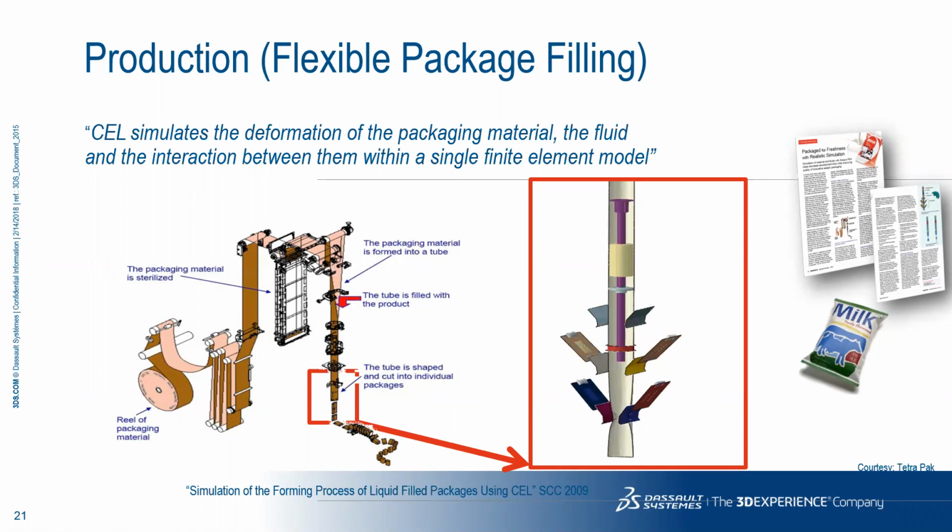So this was actually done by Tetra Pak, and you can see the process on the right. As I said, this is a complex problem, to be able to handle so much deformation, to be able to handle the fluids as well as the solids under a single solver. So what we use is a CEL technique, or the coupled Eulerian Lagrangian technique.